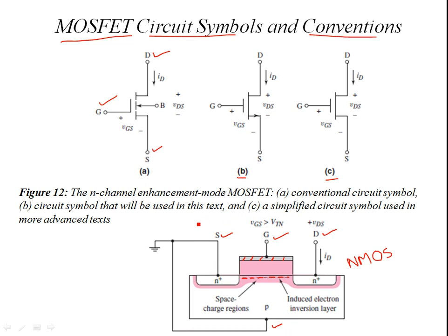Well, basically I'll say that this represents the enhancement mode of MOSFET. There is another mode known as depletion mode, which we are going to discuss in the next video, for that kind of fabrication in which you need external supply with the gate, okay. Over here you see, since this is an Nmos, and if you recall in the previous videos, we had a positive gate voltage, because your threshold voltage is positive. I mean, the biasing is such that you are accumulating positive charges over here, okay.